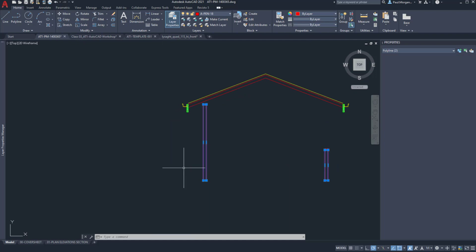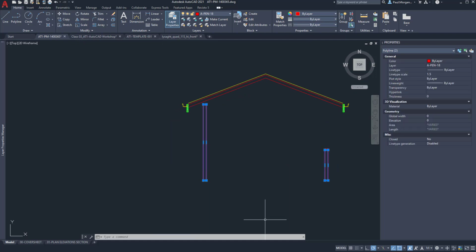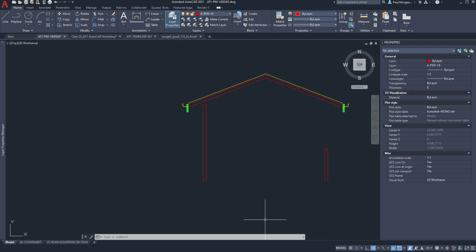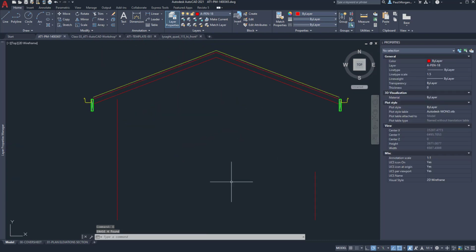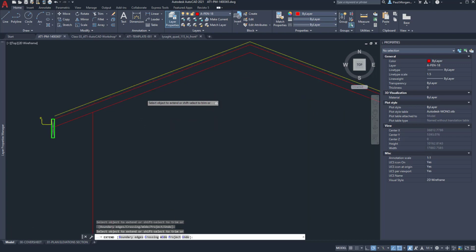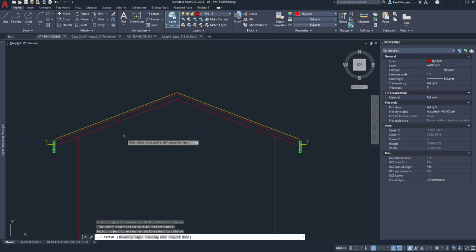And I'm going to highlight these two walls that are polylines, and I'm going to type in the command explode. That changes those back to individual lines, which then means that we can delete other components of those lines that we no longer need. So in our case, that means these lines. So we're just left with the outermost line of the wall, like so. I'm going to use the command extend that up, extend that up, like so. Okay, that looks all pretty good.